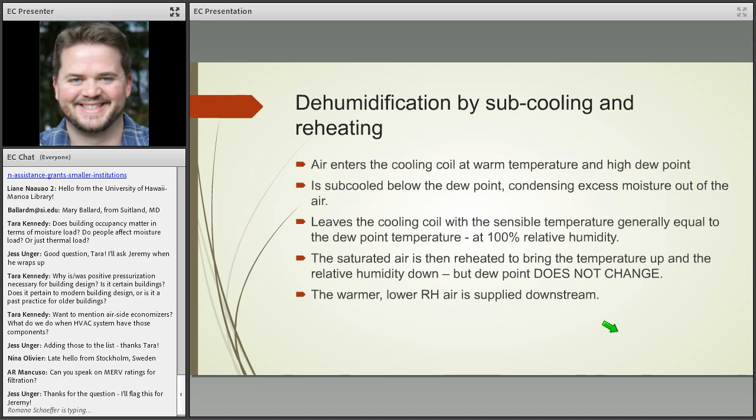It can happen in all kinds of scenarios where some institutions will have chilled water and hot water in terms of cooling and reheat coils. Some institutions, instead of using chilled water, will just be using a straight up direct expansion or refrigerant based system as their cooling capability. But the key here is that we are working through the psychrometric process to understand that we can remove moisture from the air and then change the temperature condition of that air before we send it back out to the space.